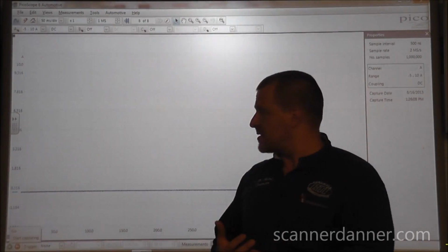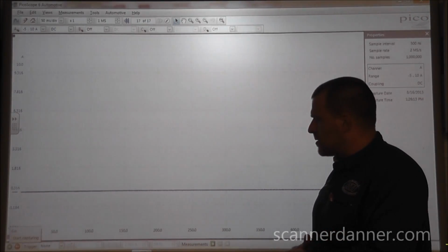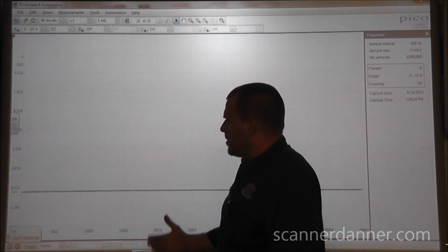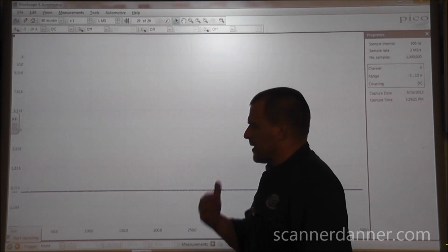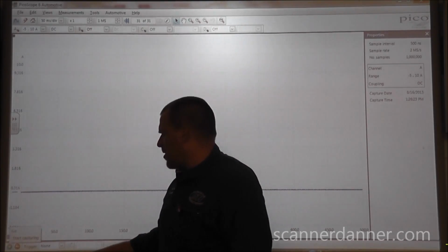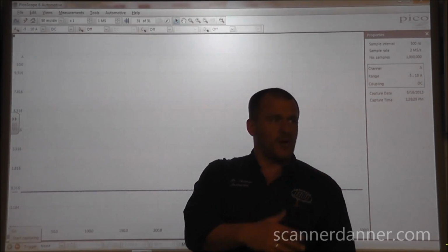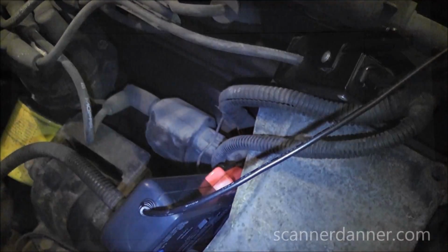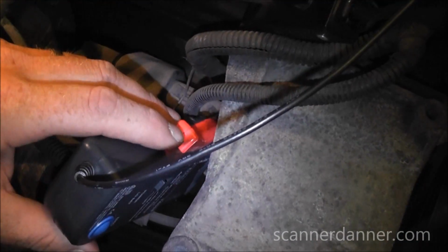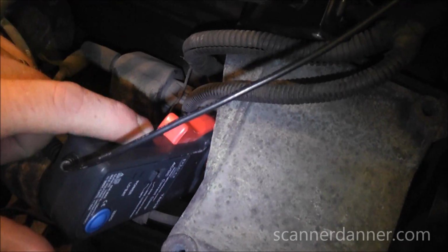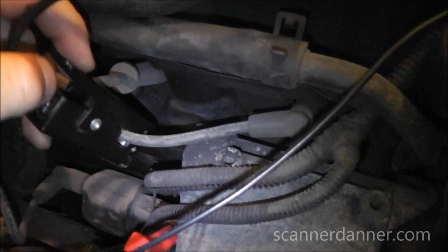Okay, what I want to do for this last segment, and we'll do more of these as we continue through this, is show you guys how to do triggering off of separate channels. So really our focus today was on trigger and time base, and so I think this will help. So what I'm going to do is set my amp probe back to the ignition coil, my low amp probe, and I'll get you guys a shot of where those are at. Okay, for this one, back to the ignition coil. For channel A, all of my coil firings here, and then connected to a plug wire with my sync probe.